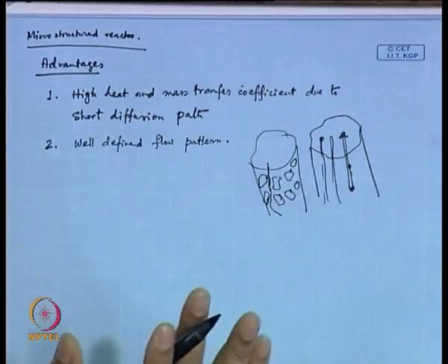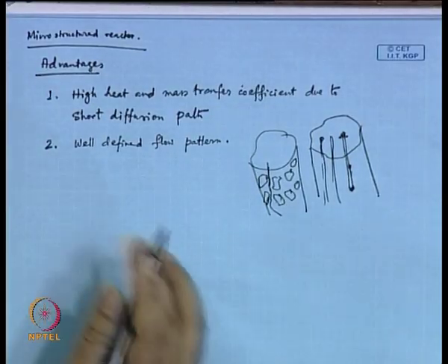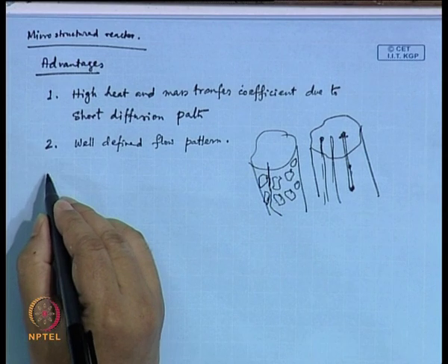And if there is too much of a reaction than what you want, there could be a possibility of thermal runaway. That means, if it is exothermic reaction and too much of heat gets generated, that you do not have any procedure to control, then the catalyst would be spoiled by that heat. So, these problems are there. In case of microstructured reactor, you can get rid of these. Anyway, these are some of the issues that we already know probably.